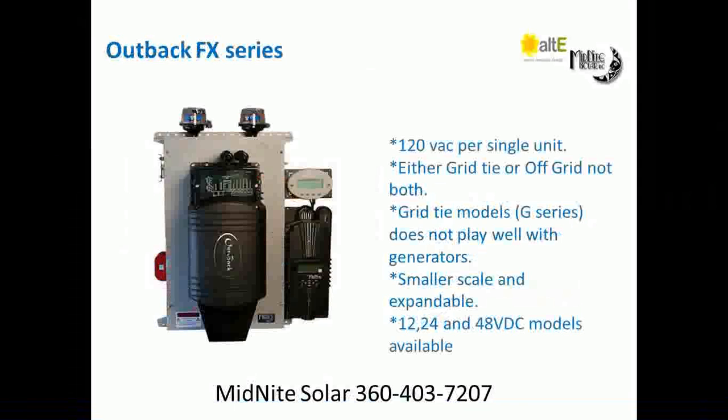The benefit of the FX series is it's a smaller scale, so it's expandable. You can stack up to 10 FXs on a system. They have a hub that allows you to plug everything together, and then the mate plugs into the hub and monitors the system. If you're doing a grid tie, you can put the Classic on there. The Classic comes with all the monitoring software. We'll talk about that a little later. Just depends on what you need.